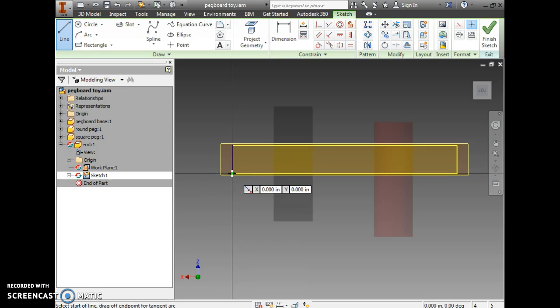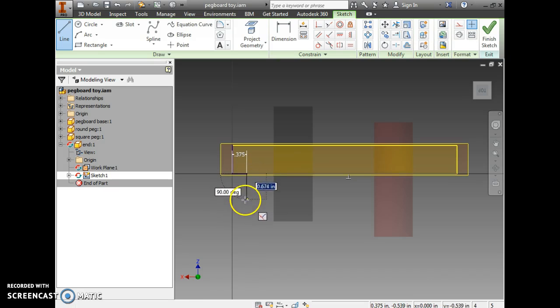Now I'm going to go in, I'm going to create a dado cut, and a dado cut is a special groove that the base sits in for support. And the dado cut's going to be half the thickness of our material. Our material is 0.75, so half that thickness is going to be 0.375. So I'm going to go into the right. I'm going to actually type this in so that I know that it's accurate. 0.375. Now I'm going to go straight down.